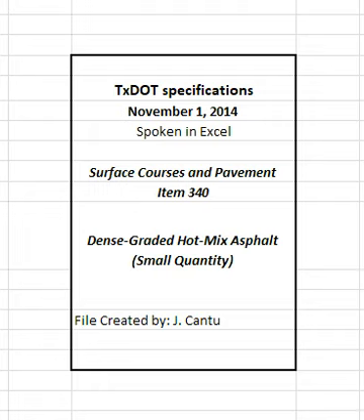2.1 Aggregate. Furnish aggregates from sources that conform to the requirements shown in Table 1 and as specified in this section. Aggregate requirements in this section, including those shown in Table 1, may be modified or eliminated when shown on the plans. Additional aggregate requirements may be specified when shown on the plans. Provide aggregate stockpiles that meet the definitions in this section for coarse, intermediate, or fine aggregate. Aggregate from reclaimed asphalt pavement, RAP, is not required to meet Table 1 requirements unless otherwise shown on the plans.